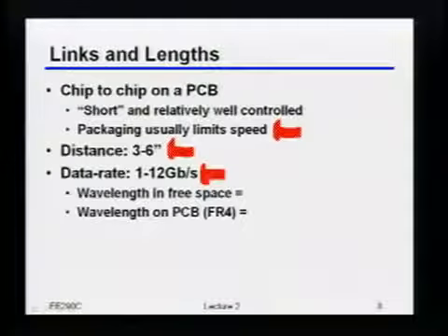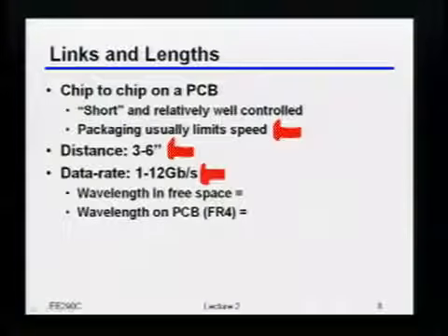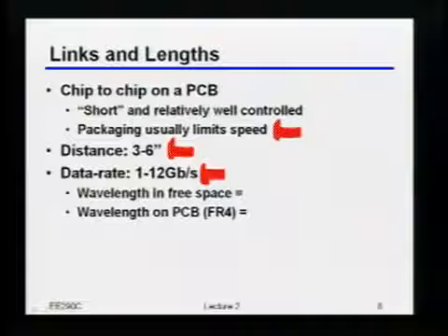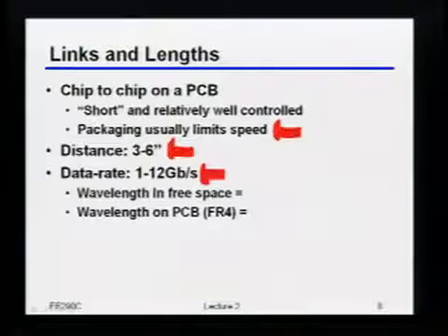What is wavelength related to? Frequency. Okay, speed of light and frequency, right? So what frequencies matter, roughly speaking, if I'm doing something from about 1 to 12 gigabits per second? 6 gigahertz. Yeah, okay, so you said 6 gigahertz, that's sort of the up end.